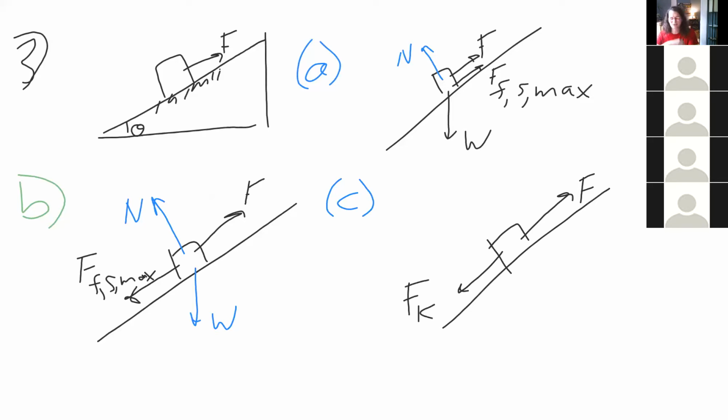There's nothing to figure out as far as maximum kinetic friction or anything like that. So the problem is pretty straightforward from here. We just have our weight directed downward and our normal force perpendicular. This should be enough to solve the problem. The one thing that I'll point out here is that in parts A and B, we're not moving, and in part C, we are moving at a constant velocity. So for this entire problem, the acceleration will be equal to 0.